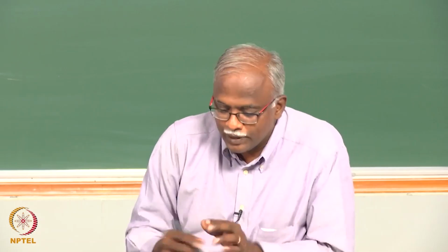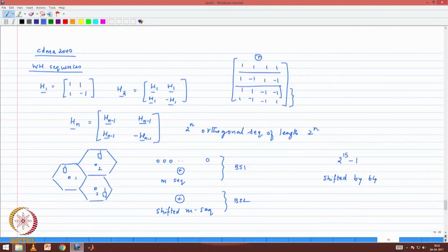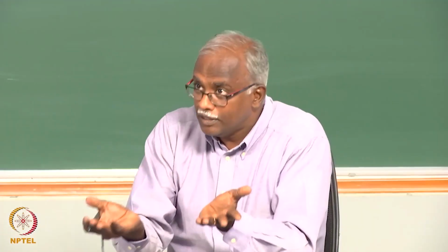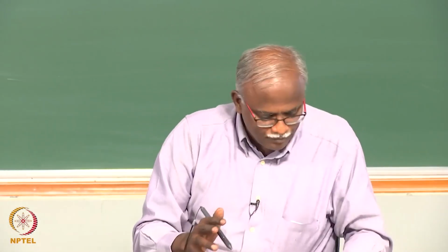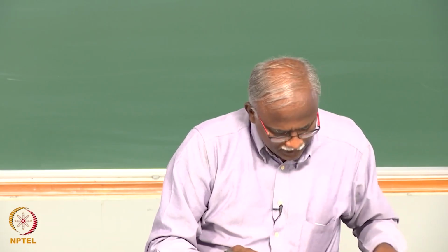So this particular code scrambled by the M sequence will never be confused with the other code shifted by 1, because the M sequences multiplying them are different. So the M sequences, rather than being the spreading sequences, have become the scrambling sequences, the basis on which you will differentiate between multi-user and multipath. So again, very important element. I hope you see the benefit.